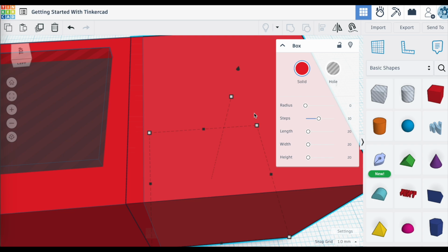go out of alignment. Now here's the other thing, again, just be aware of what your increments of measurement are set to, because the smaller the increment, the smaller the degrees of movement every time you click your arrow keys. It's a simple tip, but it's good to know when you want to have precise movements and the click and drag is simply not going to cut it.